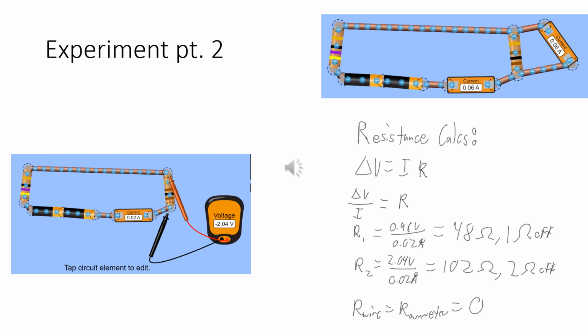And then the second image there on the top right, that's dealing with making an ammeter connect to both sides of that 100 ohm resistor. And so the reason that the current increases there to 0.06 is because you can sort of make a loop that avoids that first resistor entirely, the 100 ohm one. And so therefore delta V, 3 volts, equals 47 ohms times the current. If you make that loop that doesn't involve the resistor, from there obviously you get 0.06 amps.